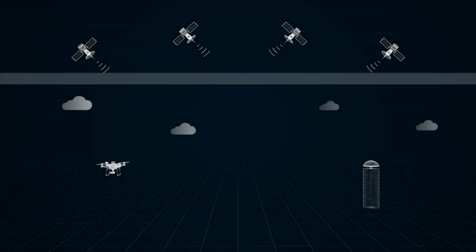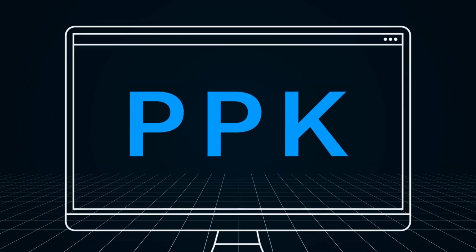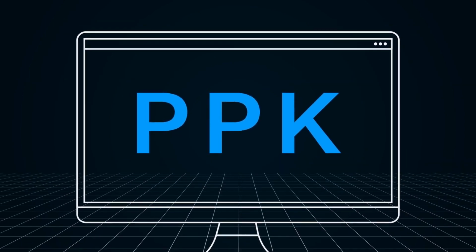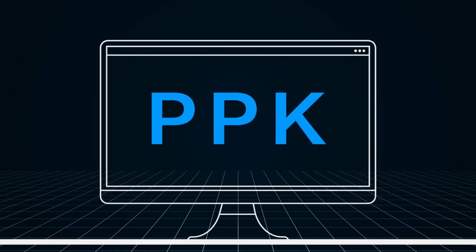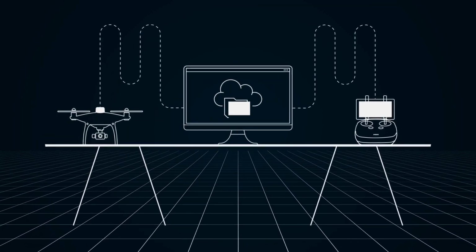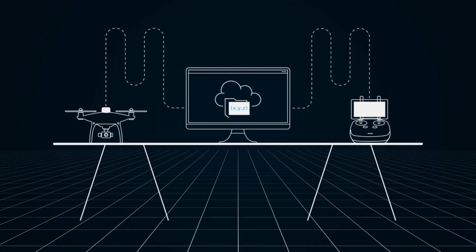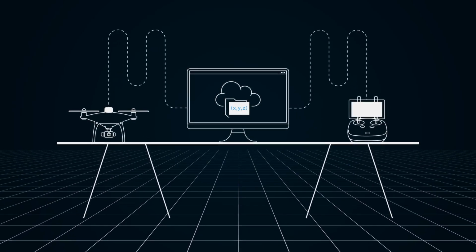However, signals need to be received all the time when using RTK. The drone may be unable to receive the signals due to the environment effects or no internet connection possible. In this case, we can measure with PPK technique, which means post-processed kinematic. After the positioning measurement, we use software to process data collected from the drone and the base station to compute the accurate position of the drone. So this technique is not performed in real time.